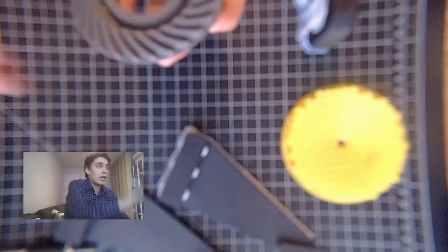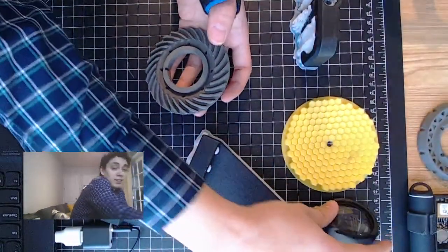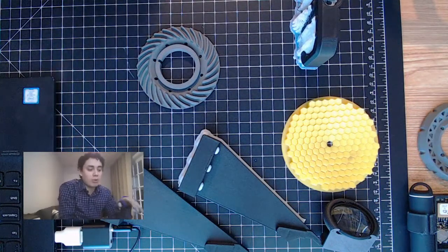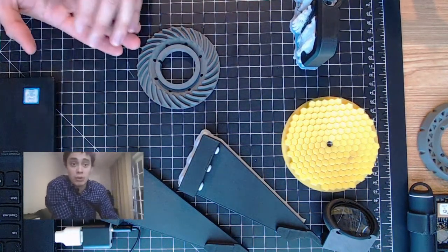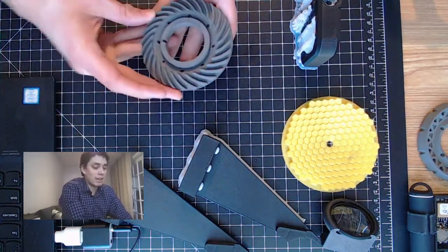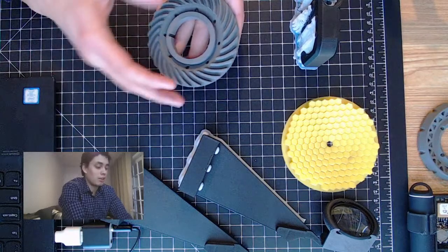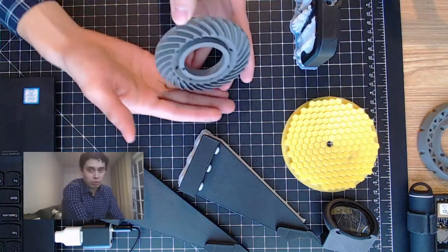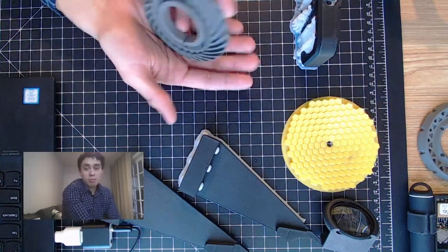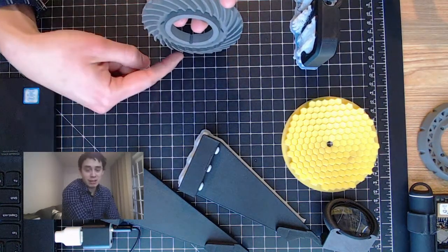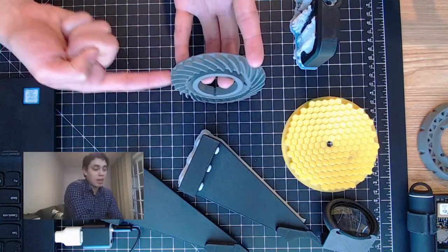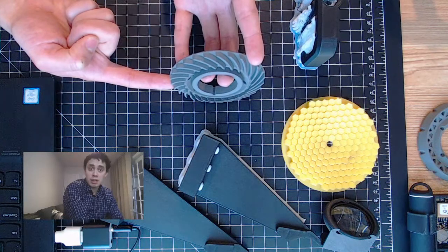As I said before, this number of layers is defined by the layer thickness, and there's a limit to how many layers you can have depending on how shallow your part is. If I wanted a much smoother transition on those layers, I would probably have had to print this part perpendicular against the build plate, instead of flat, so that I have many more layers describing that object in my printer.